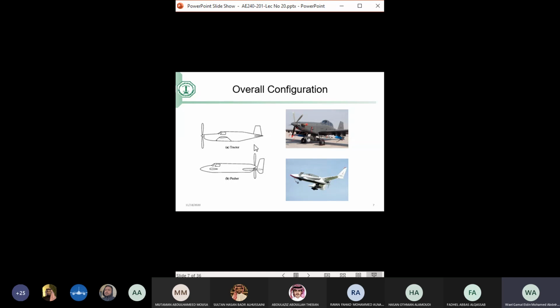Whereas if you have the propeller here and the engine here in the back, this will improve the pressure gradient in the back. We will not need that thing. We are not worried about the separation of the air on the trailing section. So most aircraft that have a pusher type, you will see they don't have the very long tail cone. Just put the propeller and end the fuselage in here. So these are all factors and they are contradictory, but it's up to the team to decide which one is the most important for our design.